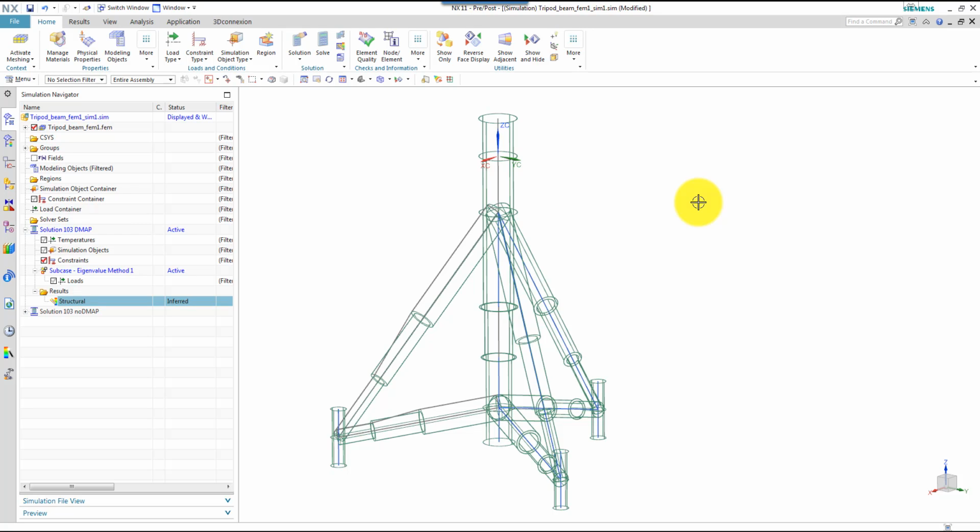These will have each 6 degrees of freedom. So that means I will have a reduced mass and stiffness matrix which has the size 30 by 30. In addition, I want to add 3 fixed interface normal modes. That means component modes that I will have when I keep my external nodes fixed. And I'll show you how to set it up.